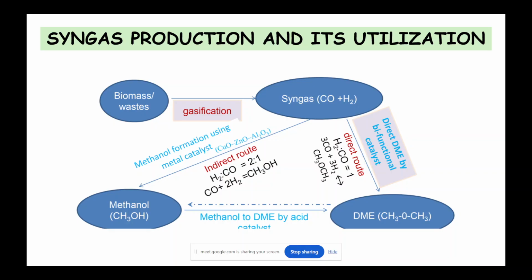In gasification, you supply a controlled amount of oxygen, or levels similar to the stoichiometric quantity required for burning. In pyrolysis, you supply a deficient amount of oxygen, much lesser than the actual required value. Depending upon this, the composition of the gas is affected.